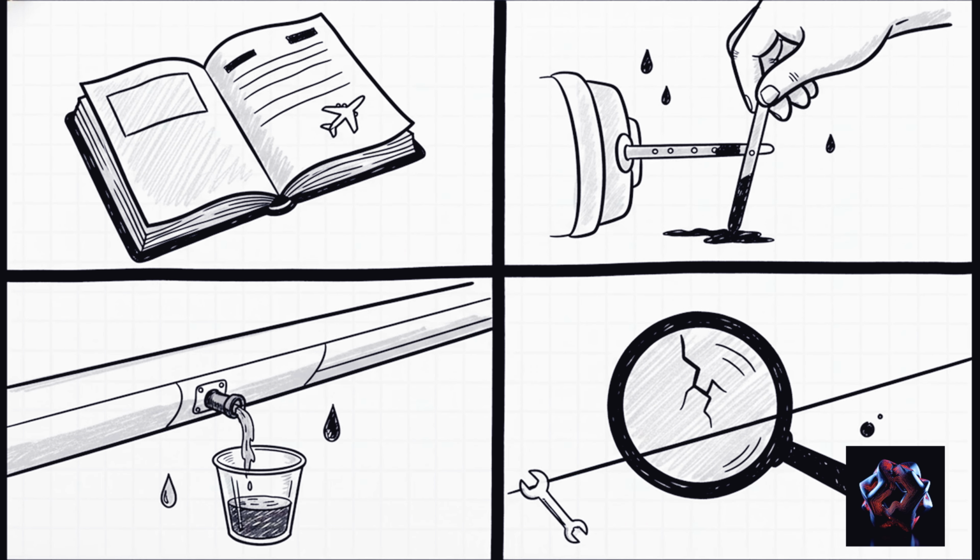A proper pre-flight is super methodical. You're always following the manufacturer's specs right out of the pilot's operating handbook, the POH. You're visually checking fuel tanks and oil to make sure they're at the right levels. You're draining a tiny bit of fuel to check for water or dirt, because trust me, water doesn't burn too well when you're 1,000 feet up. And of course, you're looking for any missing parts, little nicks, or just general damage to the airframe.